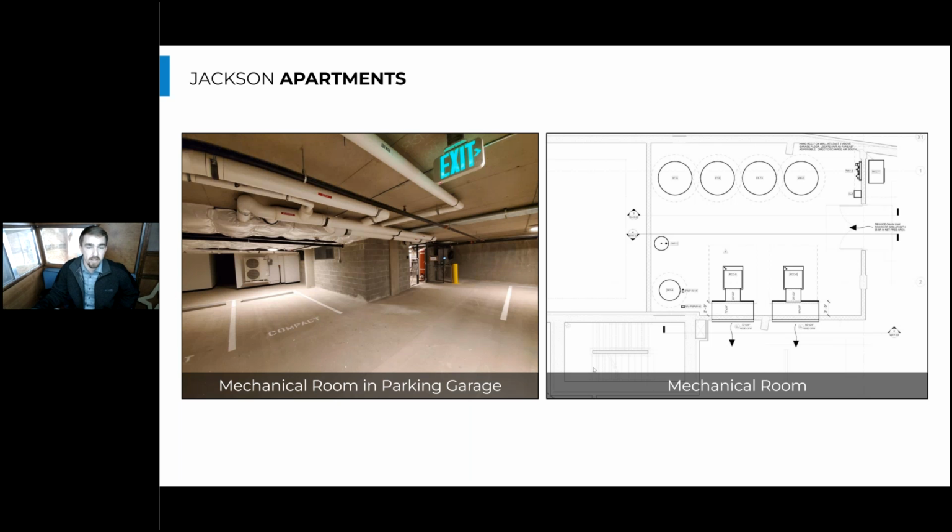So what we're doing here by placing them in the garage is we're putting them on the bottom floor, and the air that gets sucked into those heat pump water heaters has to be drawn through 3 floors of this garage. And as it does that, it passes over this semi-warm cement, and the heat from the cement is actually transferring into the air and acting as a buffer. So even if you have a really cold night in Seattle, the overall garage temperature will be warmer because that cement has held on to the previous day's heat, as well as the heat from the earth, because it's 3 stories down into the ground.